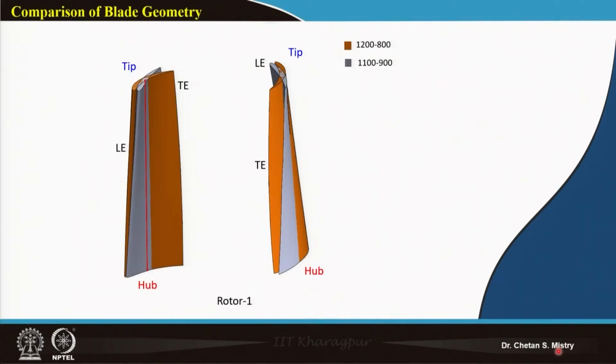So, in the last lecture we started discussing the design of rotor 1. We have done our calculation at the mid station, at the hub station, as well as at the tip station. Then we discussed how to distribute our total pressure along the span at 3 different stations, such that we take care of all the constraints we have defined, in terms of diffusion factor, de Haller's factor, and camber angle, for this kind of configuration.